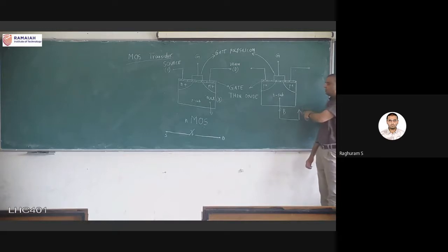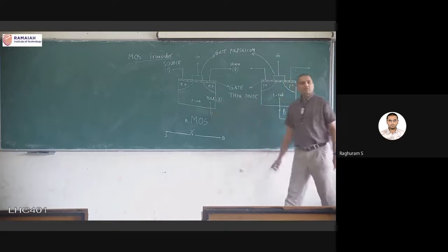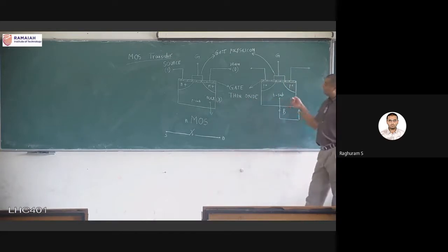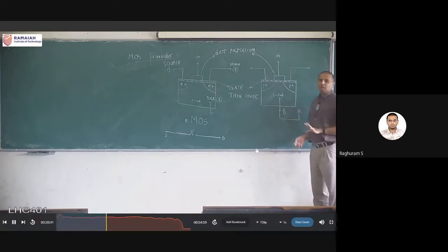So upward arrow generally means VDD. Down arrow, this we have seen, generally means ground. So the fourth terminal connection is there. It's not left floating, but we don't control it. Generally, whenever they're doing the fabrication, if they know it is a digital circuit, they will automatically turn this connection off. We don't have to do this connection. So the three terminals are the ones which are under our control. We can give a voltage and we can get the output.